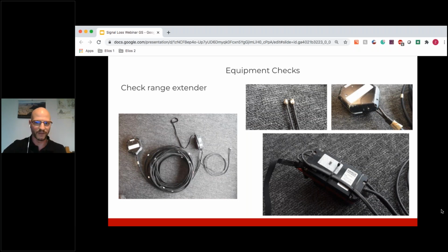If you're careless and forget that you're actually tethered to something while you're holding the remote, you might absentmindedly walk off and yank the cables as you're doing so. So if possible, incorporate some strain relief into your setup, as we did here with the battery module. You can see it's tie wrapped to the cable, just to avoid the cables pulling directly, whatever forces might be on there.